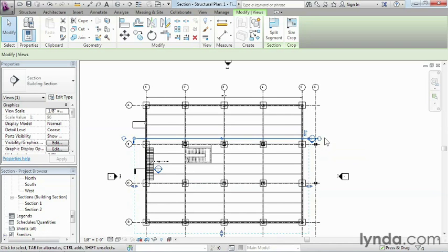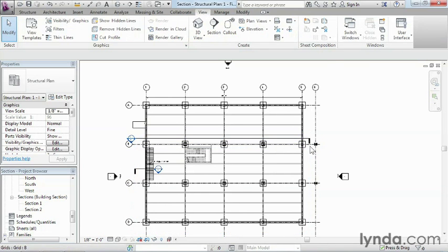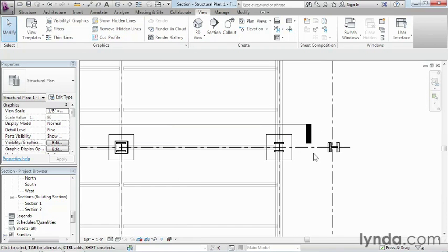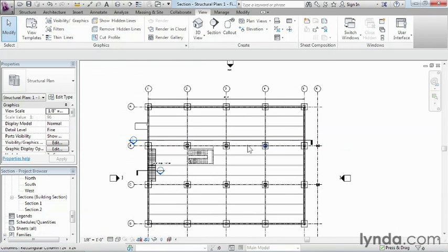Now, the last thing I wanted to do is these little circles showing up here at the ends. And if you click on the little circles, what they're going to allow you to do is flip through the different section head options that we have available to us. So if we'd rather have the circular side down here, if we would rather have this little tick or slash mark down here at the end, we could definitely do that.